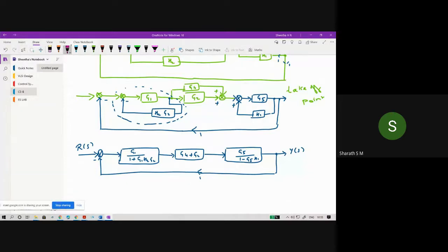This is a positive feedback. Write down the equation for that. And this one is a parallel connection, so G4 plus G2, in the forward direction. Make all those in series, so write down the product format. And then write the signal.